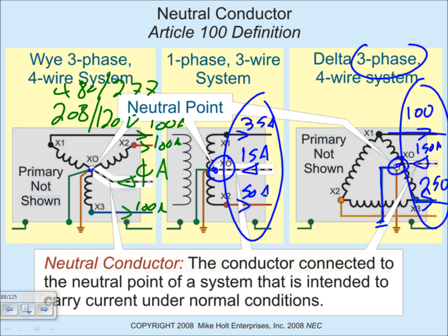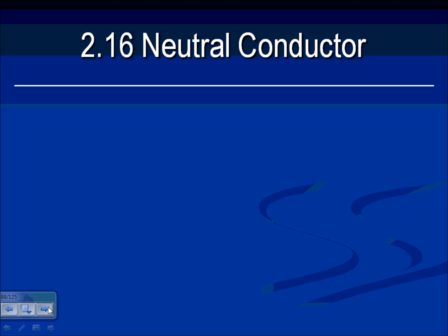Otherwise, we could make everything at 480: all these outlets, all this equipment, the printers, the plotters, everything else. The problem is that 480 is more dangerous, and the equipment has to be more robust to handle the higher voltage. Any question, guys, about that? So that's what I want to mention here.